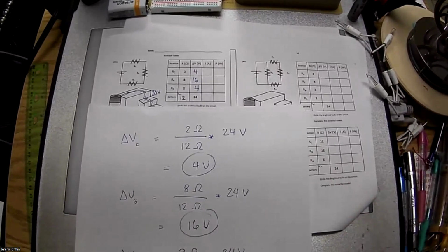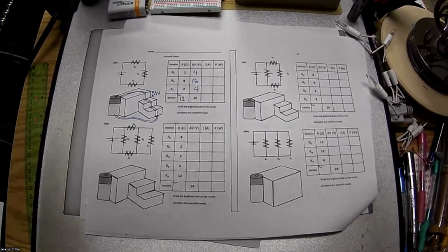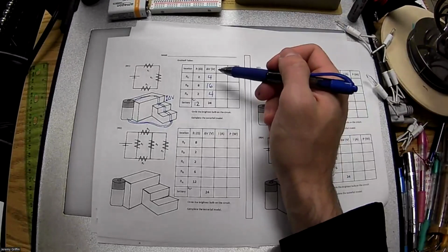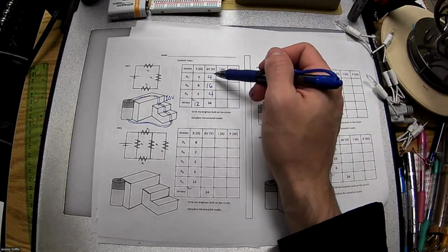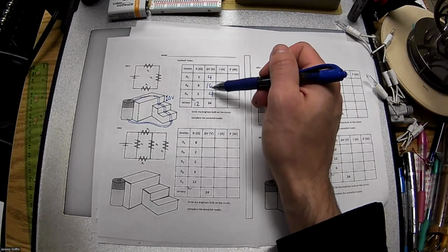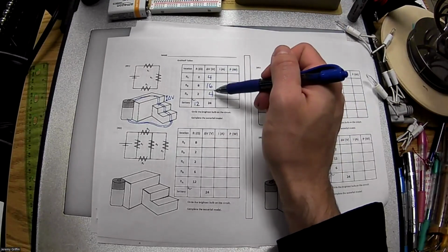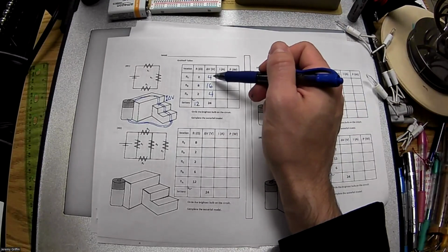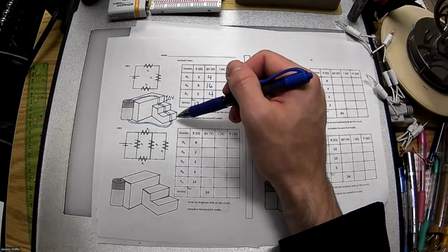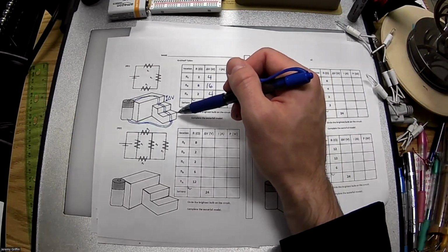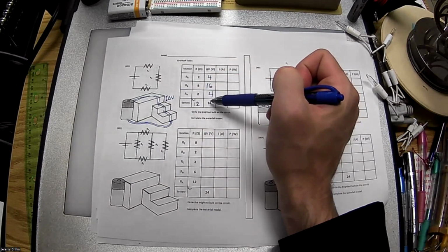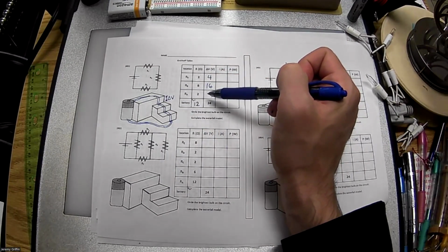Now, how do the numbers in the table we just found match up with that picture? I want you guys to see that it all matches up. Well, I've got 4 volts drop there, 16 volts drop there, 4 volts drop there. Guys, what's my total voltage drop? What's 4 plus 16 plus 4? 24. 24 volts drop. So the heights of these 3 waterfalls collectively is like 24 volts. And look at that, the battery also pumps up 24 volts. That's the loop rule.